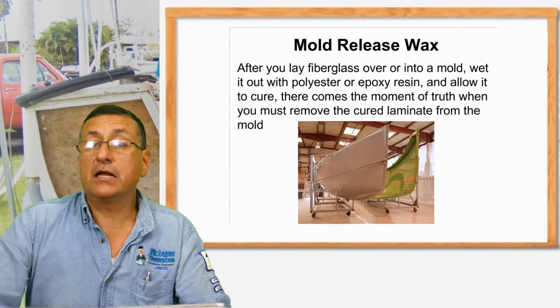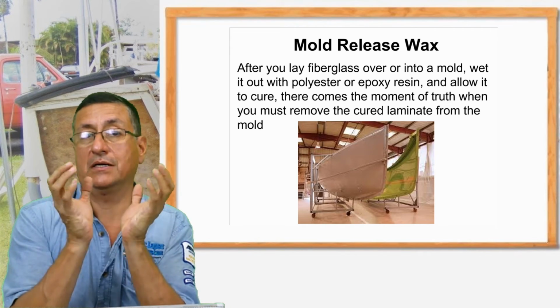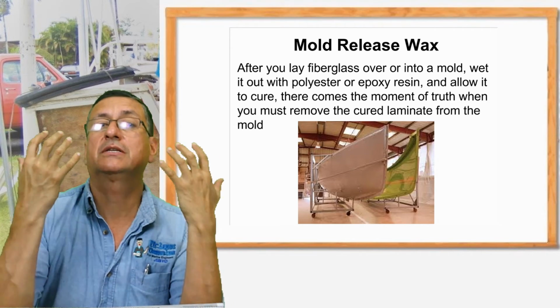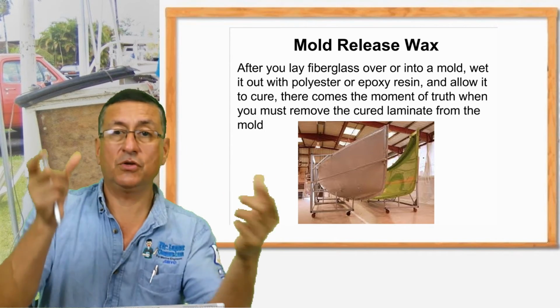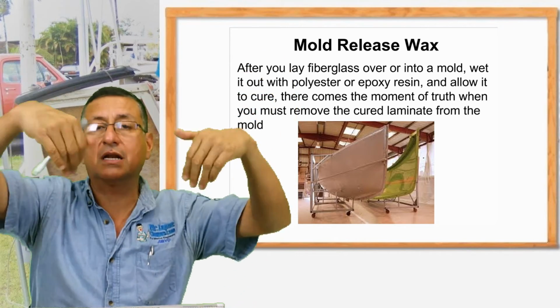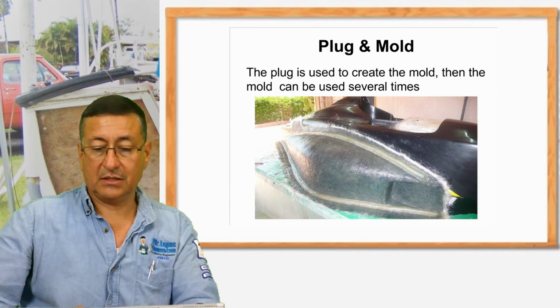All right, and there are molds that are half and half because the structure is complex. You have a half and half like this, and you put them together, and after that internally you laminate the hull that you want. This is the secret.